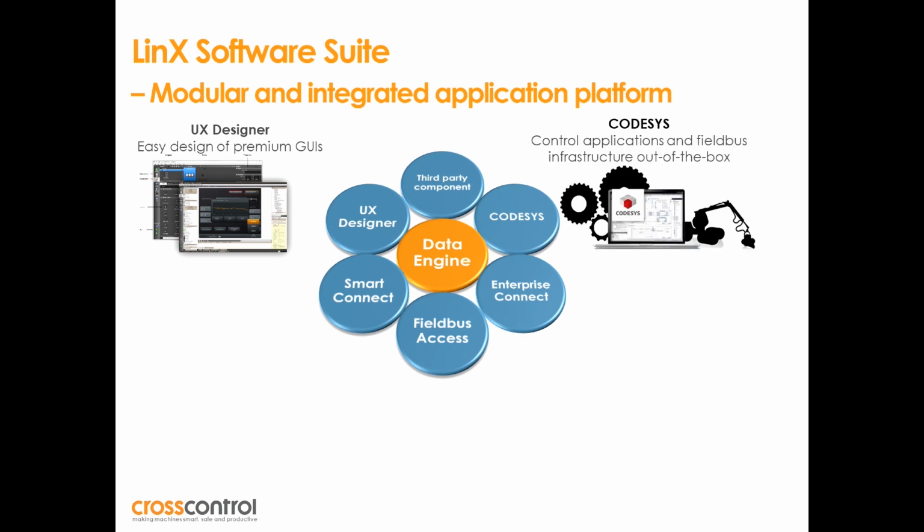We continue with Codesys. Codesys is a soft PLC, and it's very good for making control applications. It uses a different way of programming and configuring the application, since it complies to the IEC standard 61131-3, which is the global PLC standard. It also contains 5, 6 different programming languages, or let's say configuration modes, depending on your legacy knowledge and what you want to do.